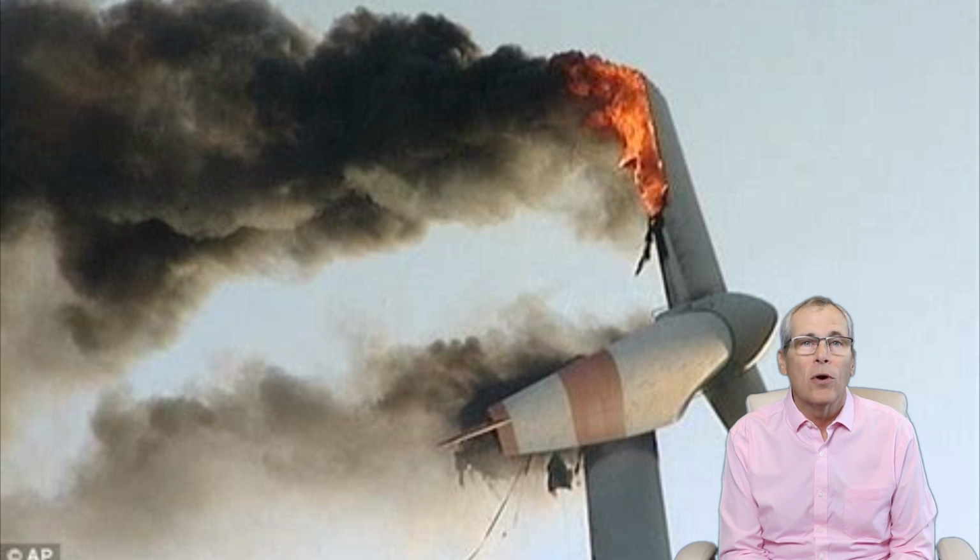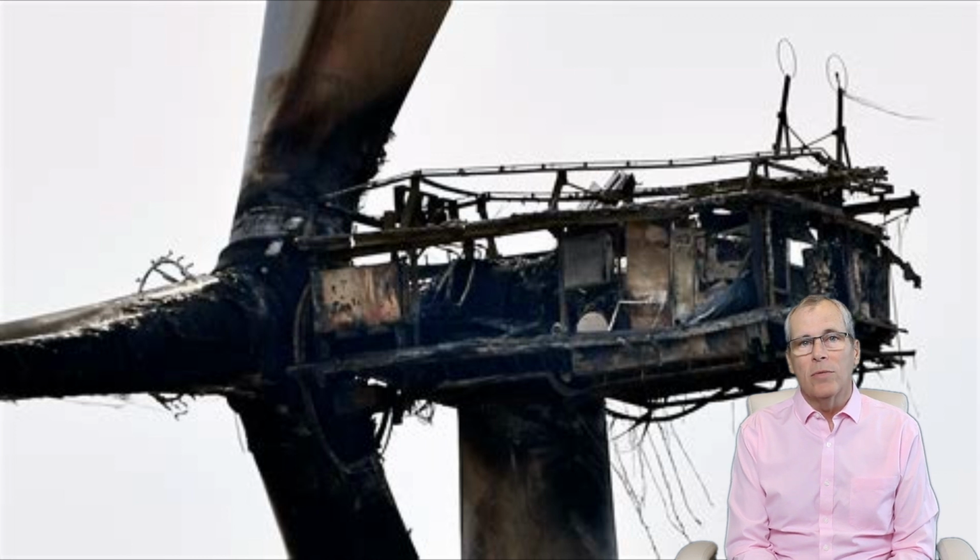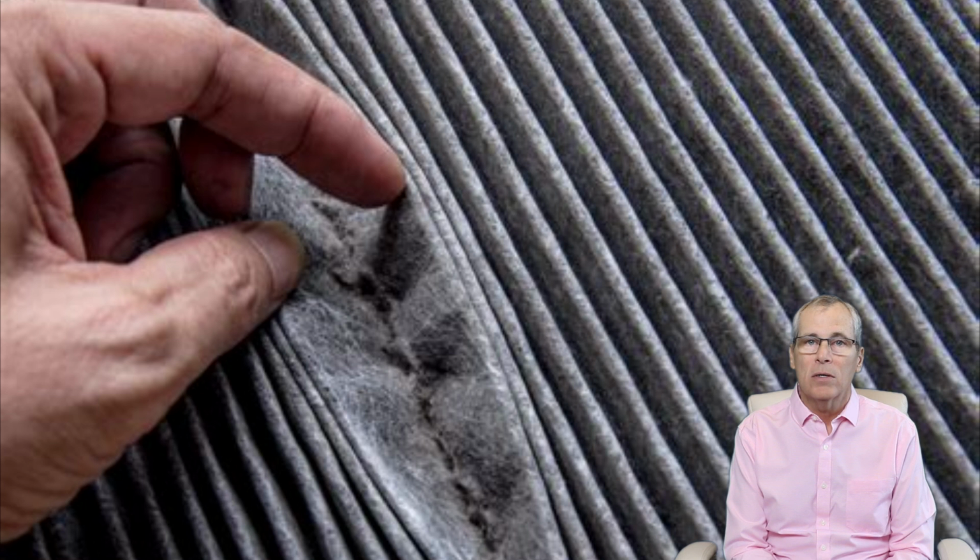Air filters are an important component of wind turbines, as they help to keep the dust and other debris from entering the turbine's internal system and causing damage. However, if the air filters become obstructed due to an unexpected increase in dust conditions, it can lead to a number of problems. One of the main issues with obstructed air filters is that it can cause the turbine's cooling systems to become less effective, leading to overheating of the turbine's components. This can lead to a fire if the overheating is not detected and addressed in time.